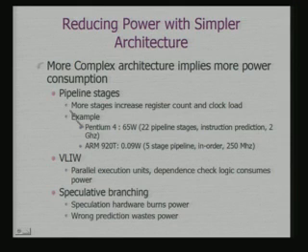Another important issue is that if you have a simpler architecture, you have less power consumption. Obviously, more complex architecture means more logic, more switching and more power consumption. Just look at these pipeline stages. More stages increase register count and the clock load. Since the register count and the clock load increase, the power consumption is bound to increase.